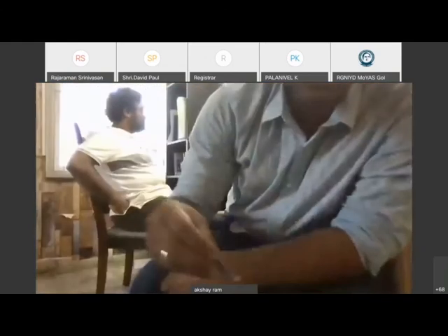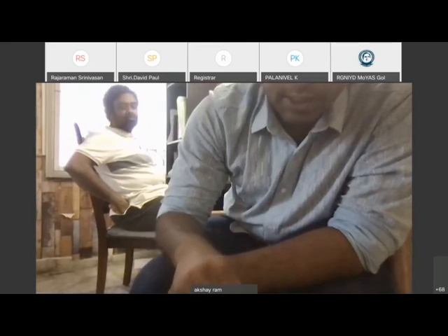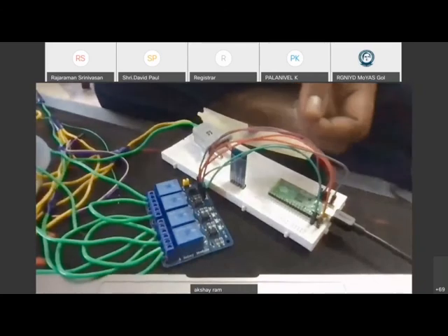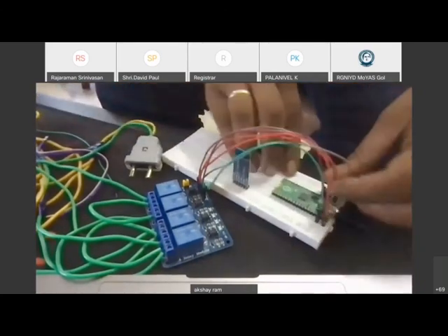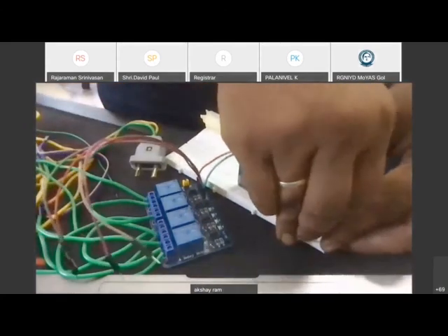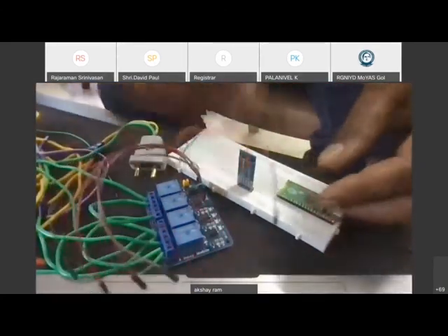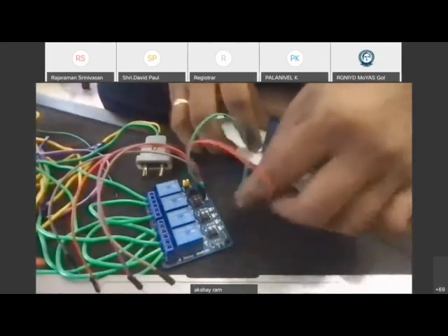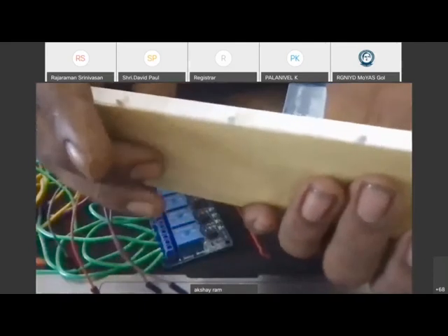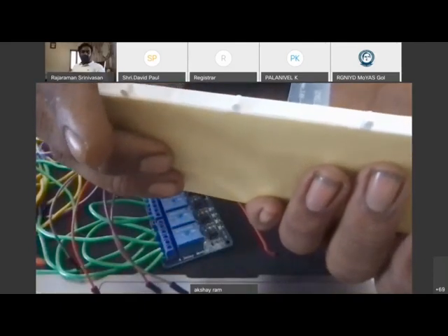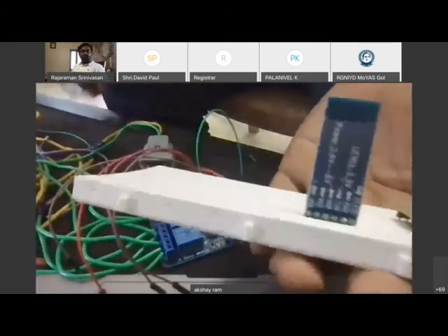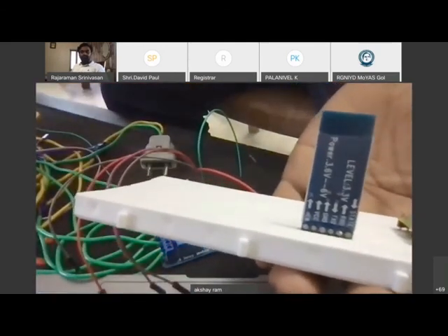So what would happen is we would have this on our Pico. VCC is 3.6 to 6 volts. So we can give it 5 volts of power.